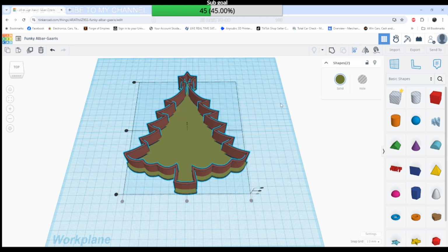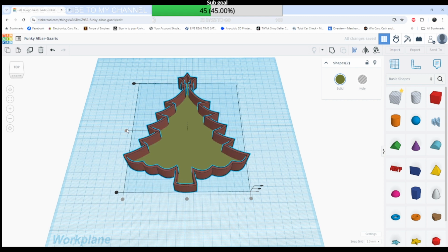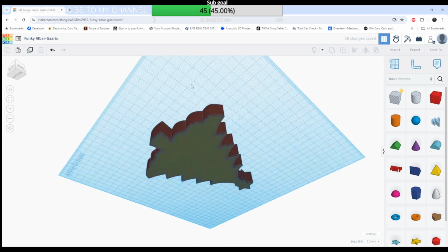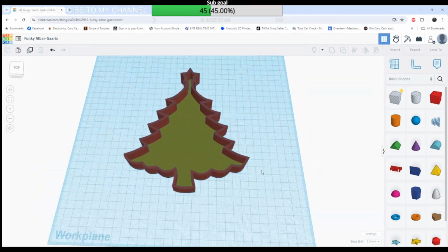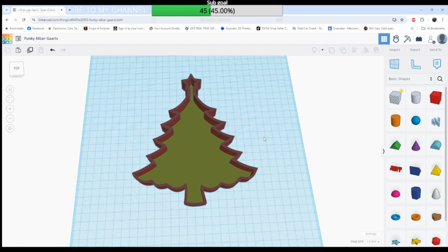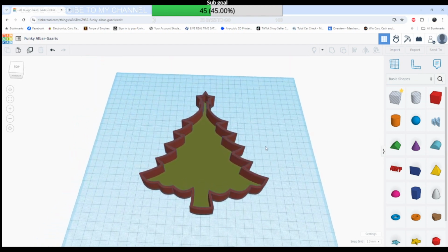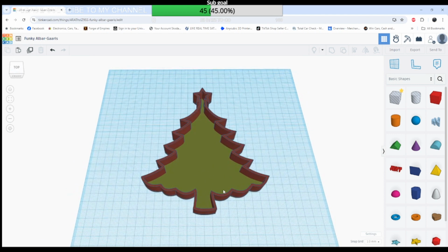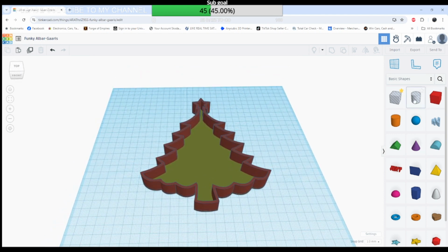Bear with me. Now, which one am I pressing? That one there. So now, as you can see, the bottom silhouette is lined up with the image that we created for the outside. And what we're going to need is a hole in the back of this tree to feed our wires in and out. So what I do, I grab the hole tool and make it 8mm by 8mm. Doesn't matter as long as the thickness is thicker than our item.